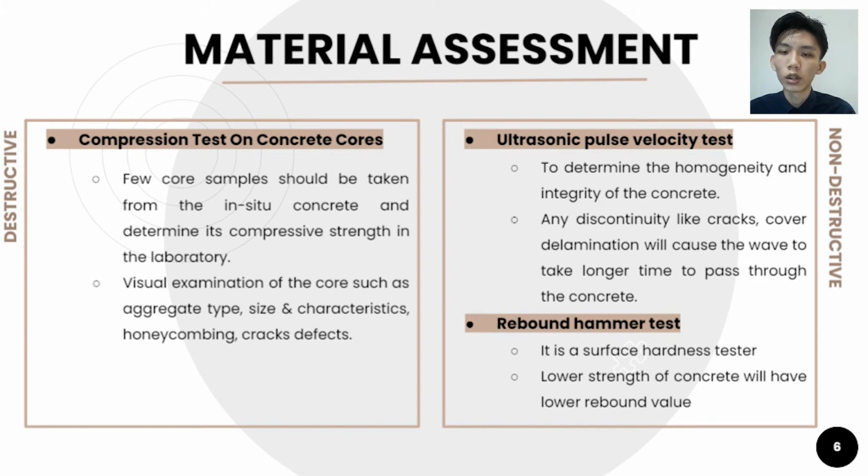This is actually a concrete hardness tester. It can be used to determine the concrete hardness. It means that the lower the rebound hammer value, the lower the strength of the concrete.